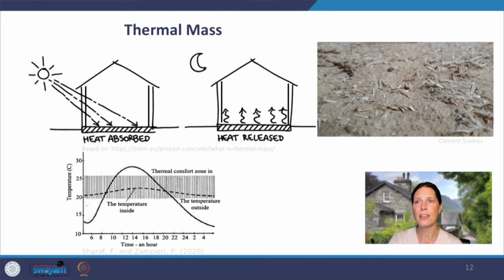To clarify, adobe is an unfired, sun-dried brick. Firing bricks makes them more compact and durable, but often thinner. One could lose the heat regulating capacity of adobe by putting it through a firing process. Also, the firing process isn't appropriate for every cultural group or region, primarily because access to significant amounts of firewood isn't easy to come by or cost efficient for most places.